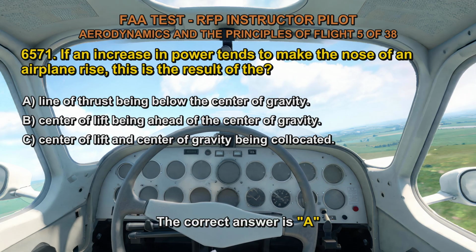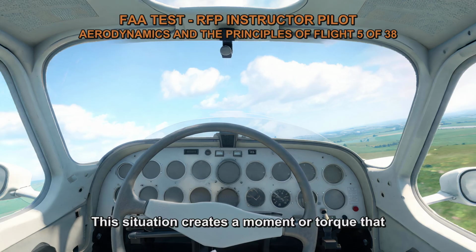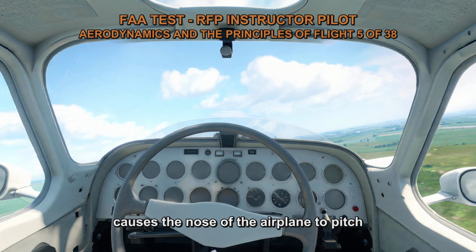The correct answer is A. When an increase in power tends to make the nose of an airplane rise, it is a result of the line of thrust being below the center of gravity. This situation creates a moment or torque that causes the nose of the airplane to pitch upward.